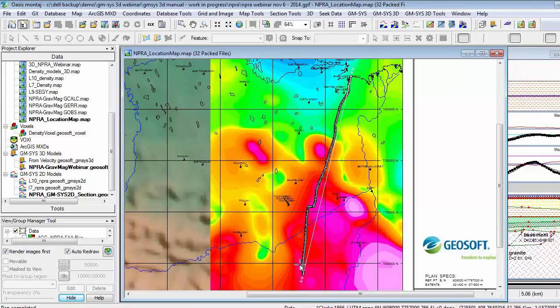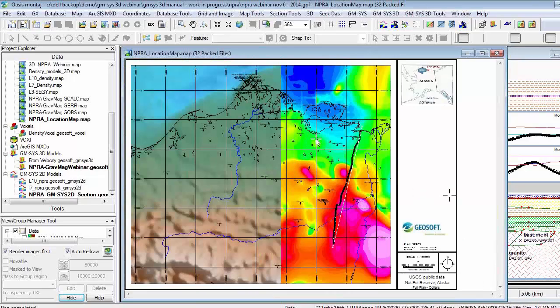That was built because there was some seismic data available in that area, so we were able to specify the geological section in that space and integrate any well information we had and other info as well. But if you take a look at the map itself, we have full gravity and magnetic data that was collected, and we also have grids depicting geological contacts in this area. That's the point where we're able to create that GM-SYS 3D model and work in 3 dimensions.